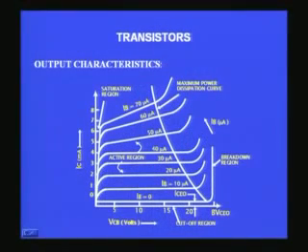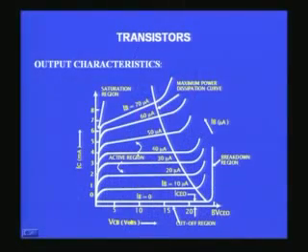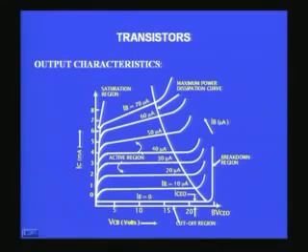This is the output characteristics of a common emitter transistor, and we have seen the active region. Now any given circuit can be positioned on the characteristics at a given point. This positioning of a transistor at a given point in the active region is called biasing, right. So a transistor has to be biased to bring it to a very specific point, which is called the operating point or the quiescent point of the amplifier, and that is what we are going to look at now.